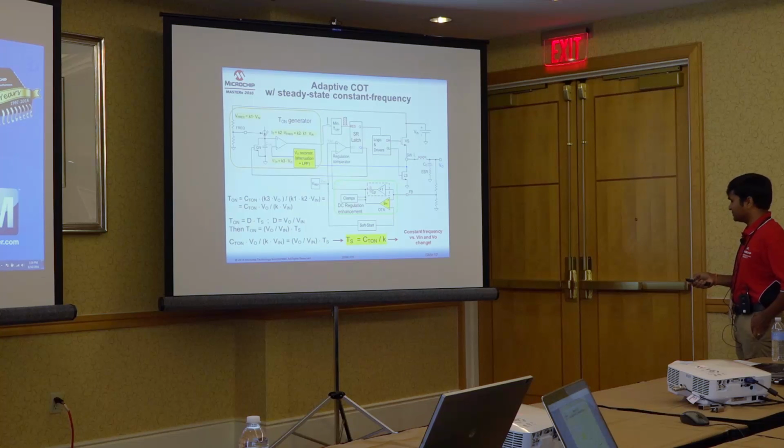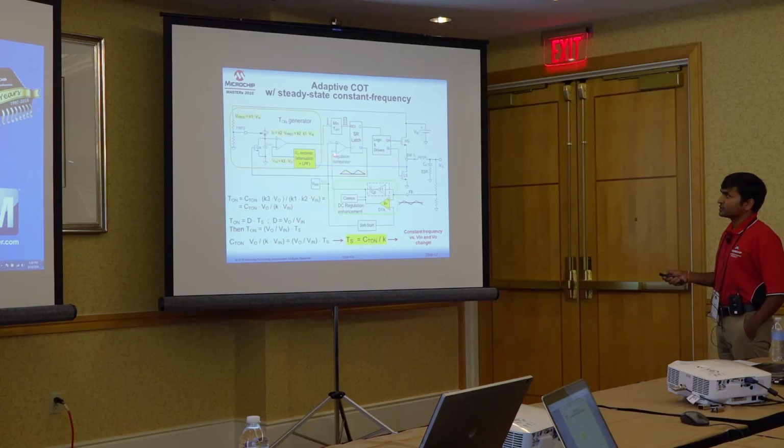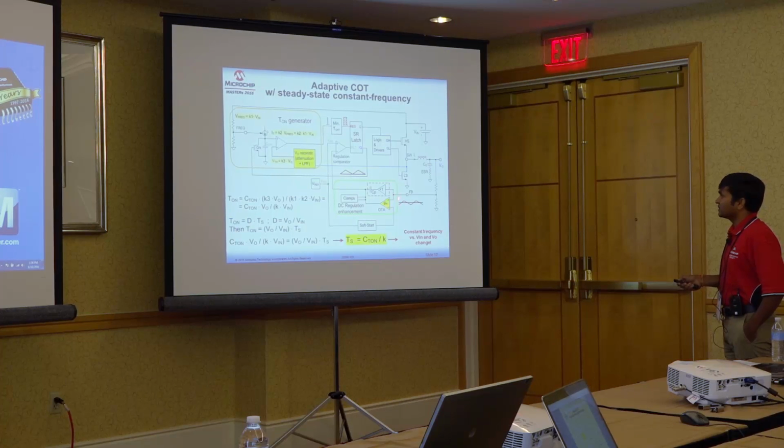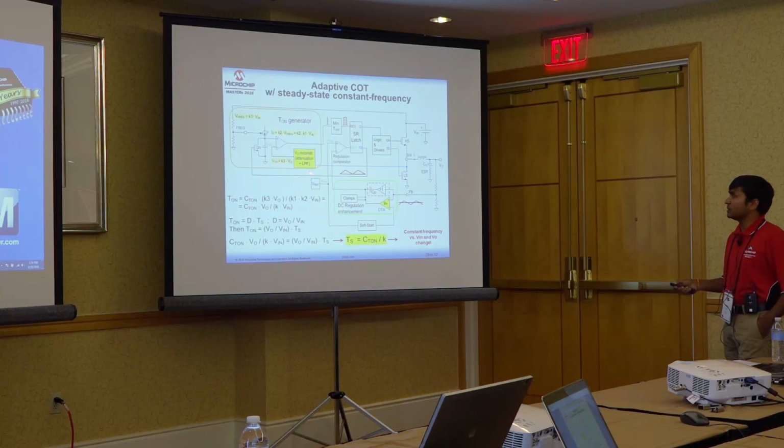The purpose of this block is that the regulation comparator requires a triangular waveform for regulation. So this amplifier, along with the bypass filter, transfers all the AC ripple from the feedback node to the output of the amplifier. It does not provide any phase or gain modification to this; it only provides DC gain, not any AC gain. It is like an active low pass filter.